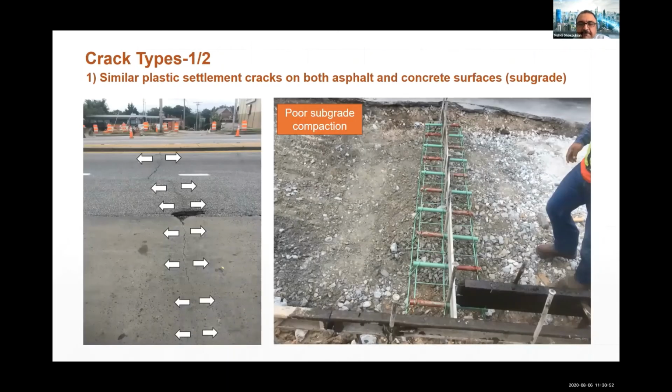All right, here are some of the observations that we had in this study. As you see here, poor subgrade compaction was observed, and even the thickness of the slab is not very uniform where they cut out the flexible pavement. It is expected that they at least have some lean concrete to level the underneath of the concrete slab.